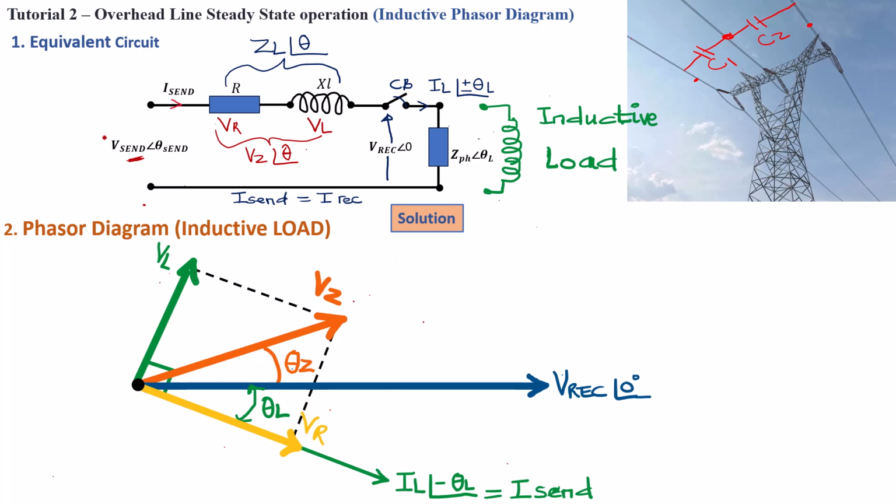Now this here is the power plant, basically our substation or the generating substation, where we're generating the voltage at 132 kilovolt, and we want to send it along the transmission line using these pylons here, and we encounter a voltage drop across the transmission line because of the reactive element of the cable and the resistive element of the cable.